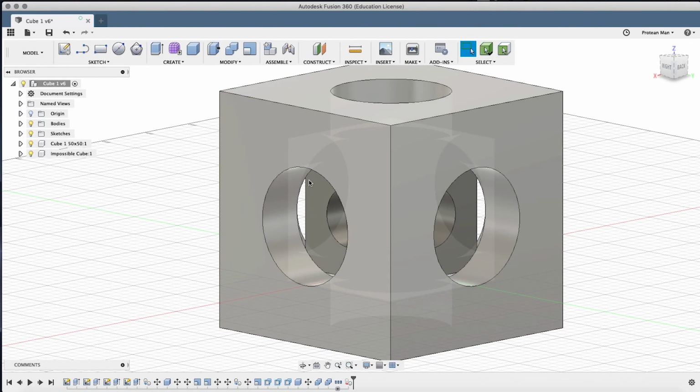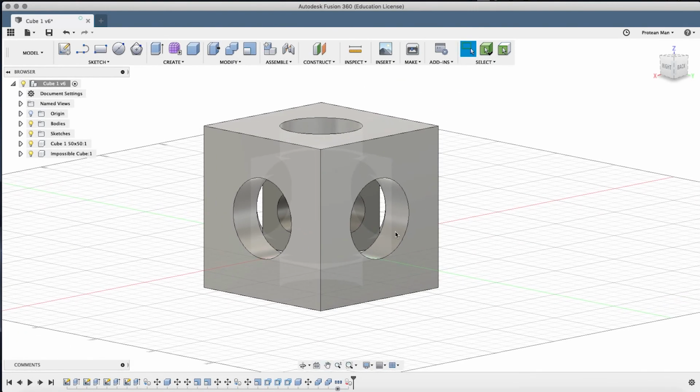And the slicing program will take whatever object you have, and for us it's this, and it will slice it into little layers back and forth, and then it will build it up in the program when you send that data to the 3D printer, which basically just sends coordinates, like GPS coordinates. And the printer just follows those coordinates and adds plastic or adds whatever material you're using to build the object.